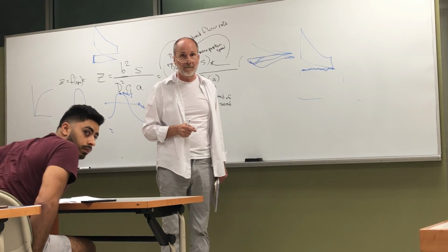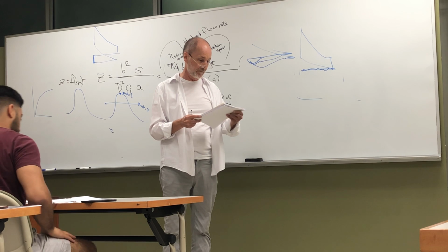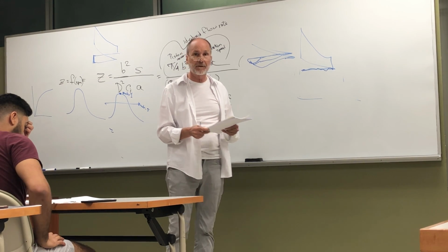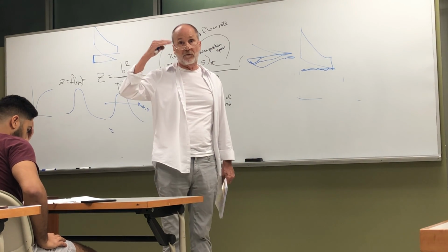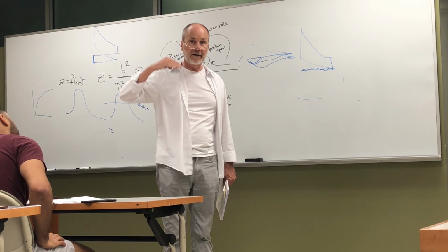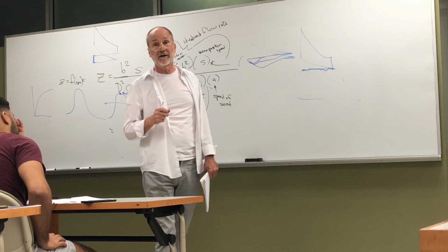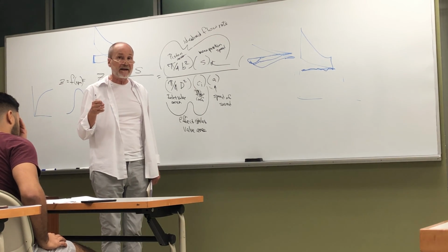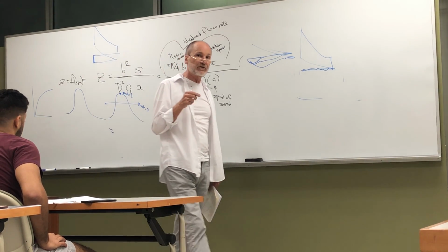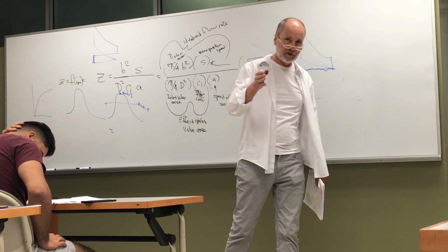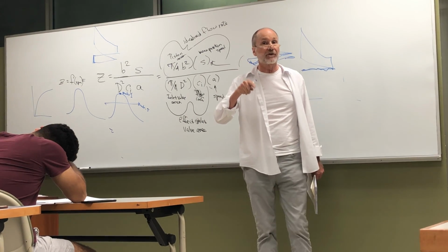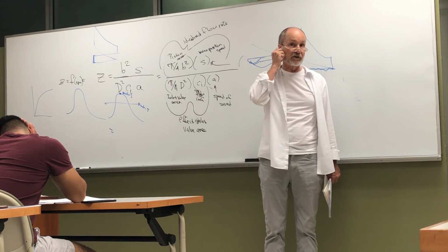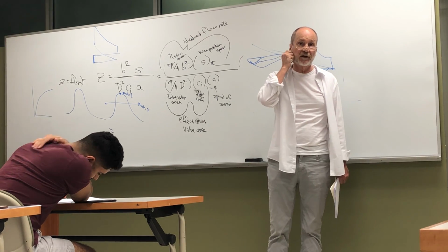What's the reason for it? It looks like as we're increasing Mach number, those waves start to change. When the density is changing in the cylinder, density and temperature, the frequency changes. That wave is bouncing back at whatever the natural frequency is for that shape and geometry, and it's changing too. That frequency is a function of temperature, pressure, and geometry.